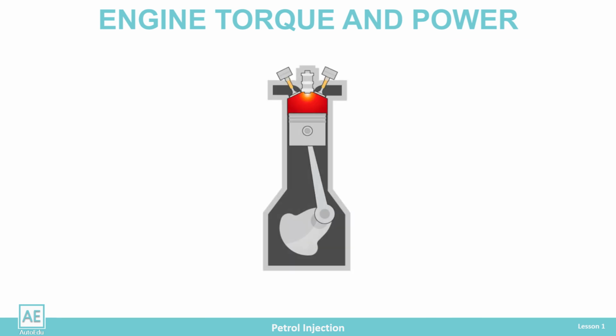In the engine, the pushing force of the piston is converted into the torque of the crankshaft and the drive of the vehicle via the connecting rod as a lever. The turning force applied to the crankshaft is the torque of the engine. The crankshaft then applies rotational force to other components, such as the gearbox and pulley.